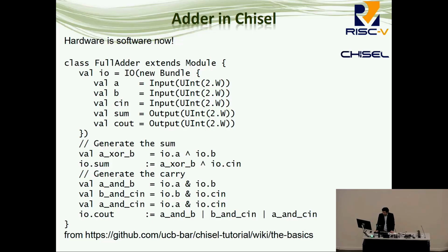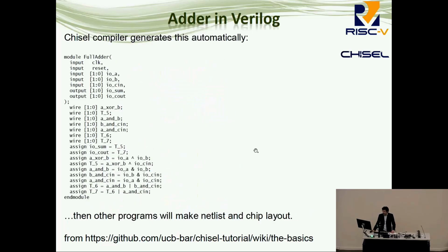So that Chisel code will then compile into something like this. This is a corresponding piece of Verilog code. And you can see instantly by looking at it, this looks like a lower level description. There's less hierarchical structure going on here. A lot of the abstractions have got compiled down into individual wires and individual logic gates sitting in the Verilog.